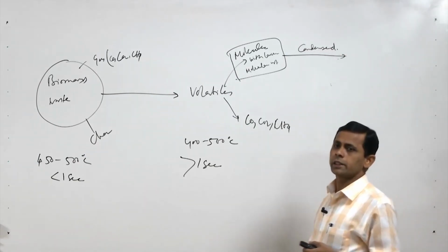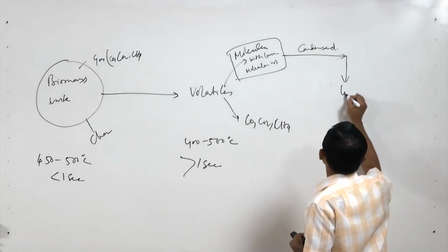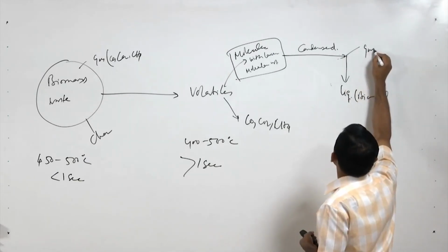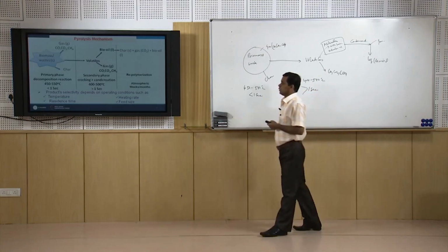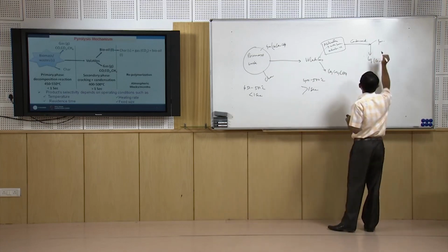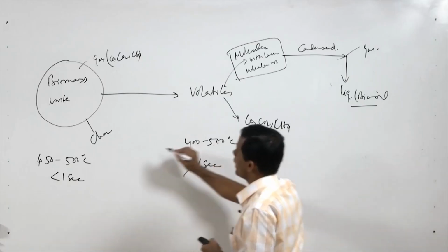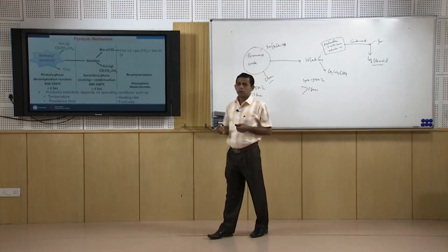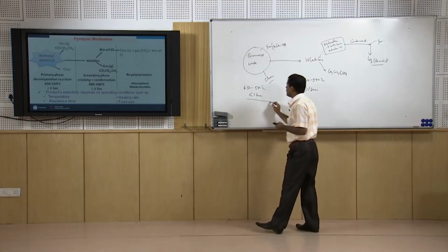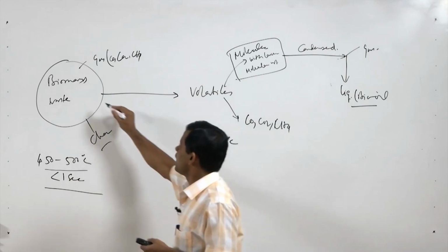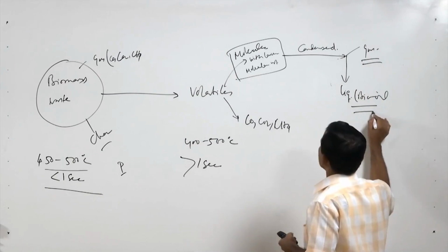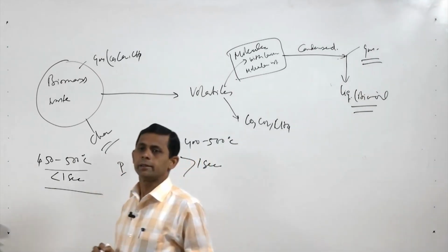After condensation, we will get liquid, that is called bio oil, and the other part we will get as gas. So, this is the mechanistic path for the production of gas, liquid and char. Now, a number of reactions are going on, and depending upon the residence time, the temperature, and the pressure in this reactor, the distribution of these products will vary.